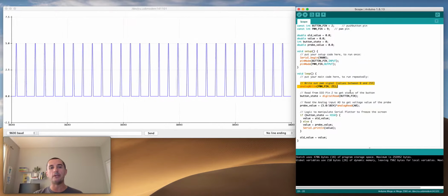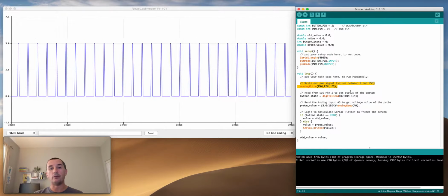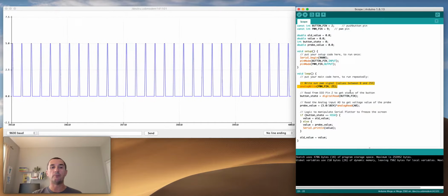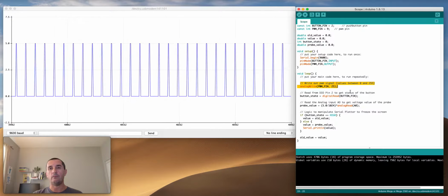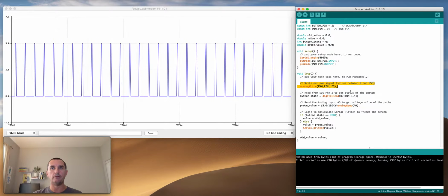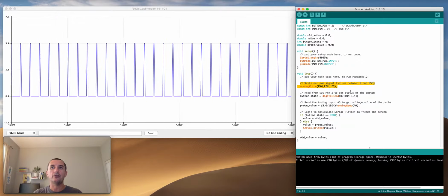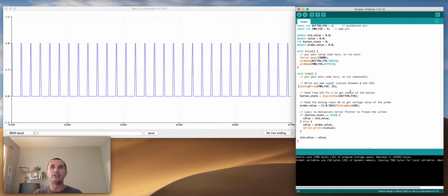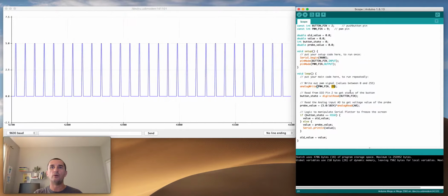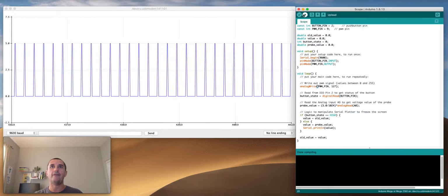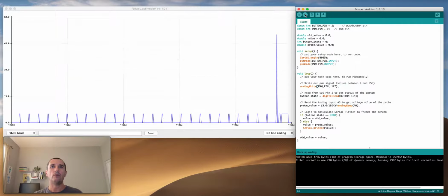But if you're familiar with PWM, you probably are thinking, well, I normally think of PWM in terms of percentage, right? And so in terms of percentage, you have to do the conversion here for the Arduino API. So to use the analog write, it takes values between 0 and 255. In our case, we have 25 there. If I change this value to 127, which is halfway between 0 and 255, and I re-upload my code, what we're going to see